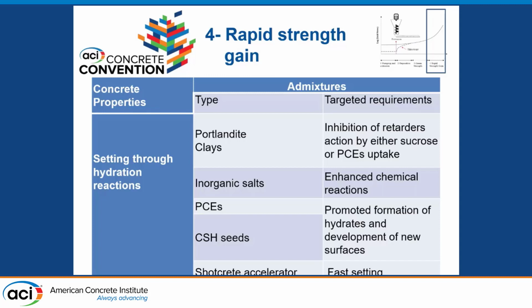So you can be using additional clays, inorganic salts, additional PCE, or CSH seeds, which are small particles of CSH that can also have an accelerating effect. And you can also use shotcrete accelerator. They really speed up the setting time.